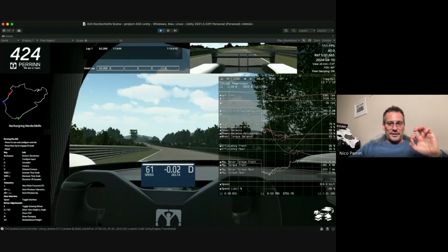Between the start of braking, the mid corner, and the exit, the amount of power we send or regen at the front relative to the total keeps changing all the time. Under very hard braking, we're 70% at the front. Why? Because we are braking hard, we have a lot of potential at the front, so we are doing our regen 70% at the front and only 30% at the rear.